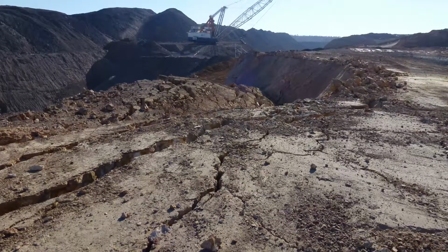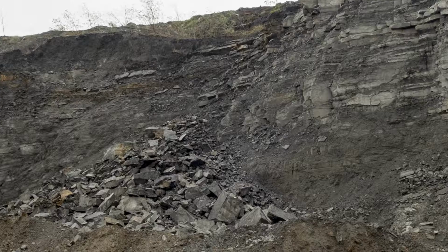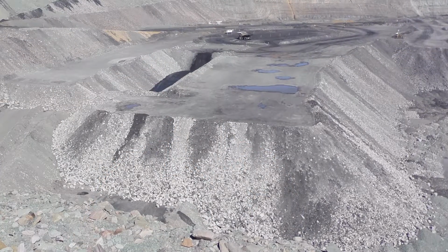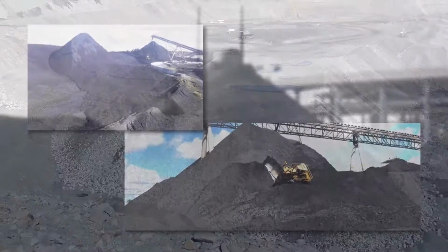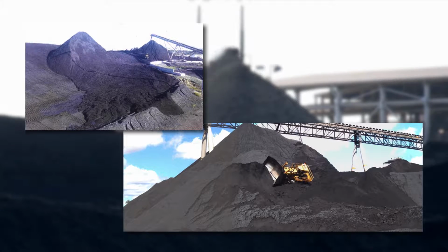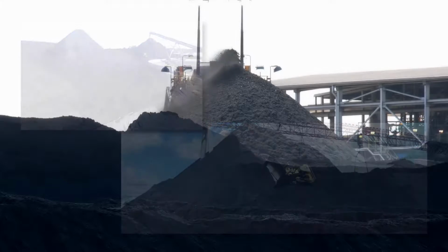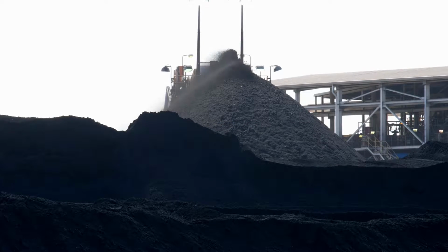As the factors that drive failure are different for excavated slopes and dump slopes, the warning signs of these failures will be different. While there will be some overlap, there will be different warning signs for high wall, end wall, and soft wall failures. There will also be similarities and differences between the warning signs for dumped slopes involving wet rejects, dragline spoil, and truck and shovel waste. Slope failures also occur in coal stockpiles. You must be familiar with the warning signs for all types of excavated and dumped slopes.